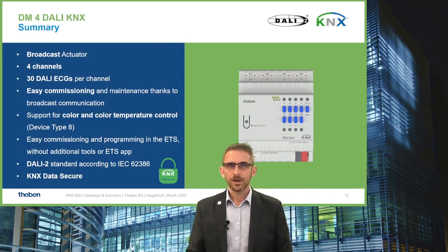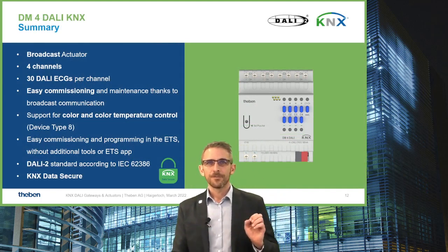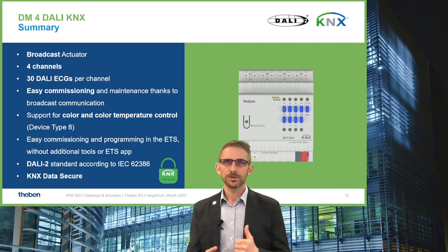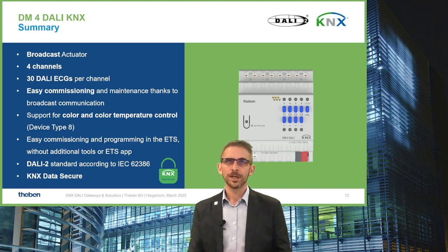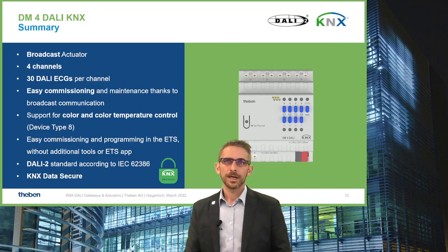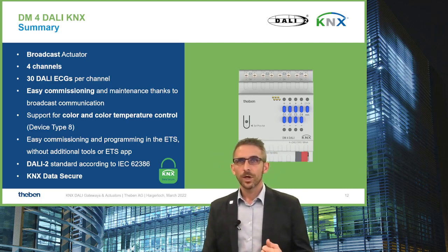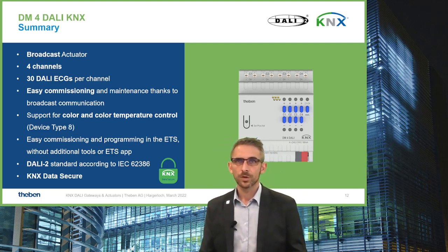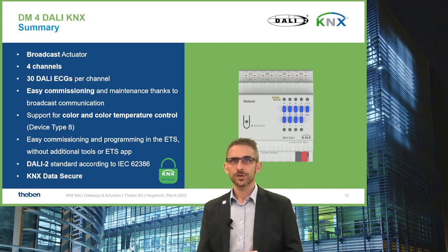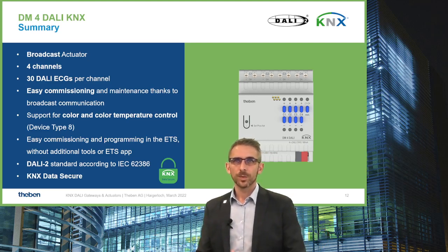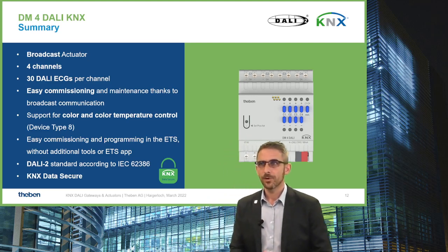So the summary of this new device, DM4 DALI KNX: it is a broadcast communication. This is very important because we do not have the need to do a DALI addressing or DALI grouping. We just connect up to 30 DALI control gears to one channel. So it's very easy for commissioning and also for maintenance. And we also have included with each channel the possibility to control the DALI devices in color temperature or in color with the currently available data point types in the KNX world.